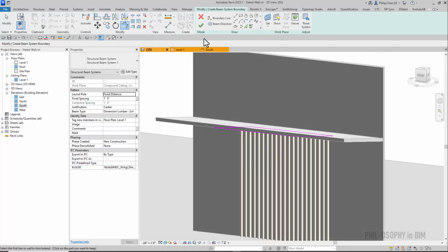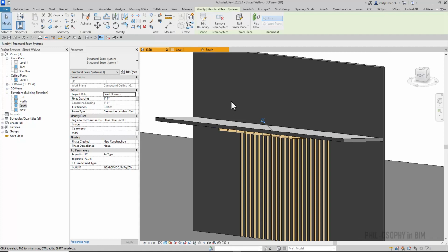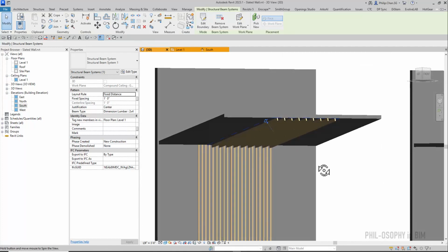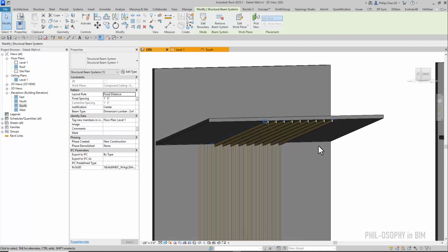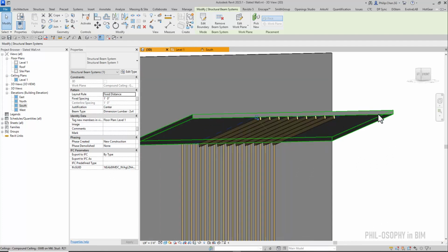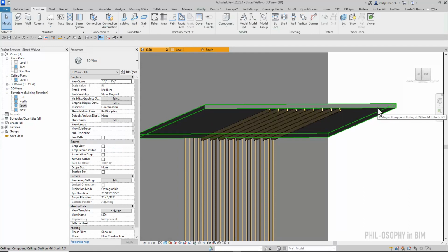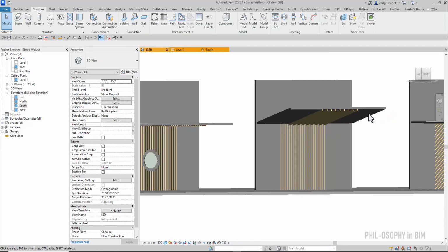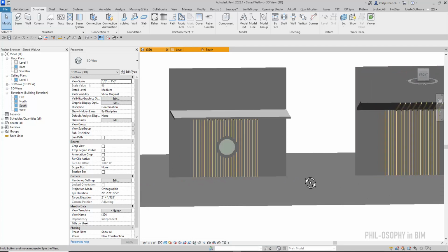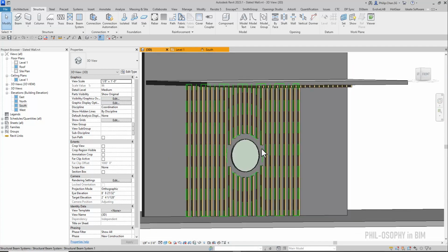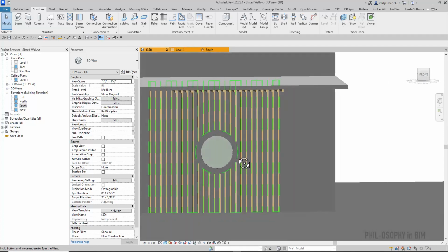Okay, and let's finish it just like that. So we can see that now my slope slash ceiling is going to follow my ceiling as well, because my ceiling is actually being used as a work plane. Okay, all right. There's one thing that I want to talk about when it comes to modeling precisely.